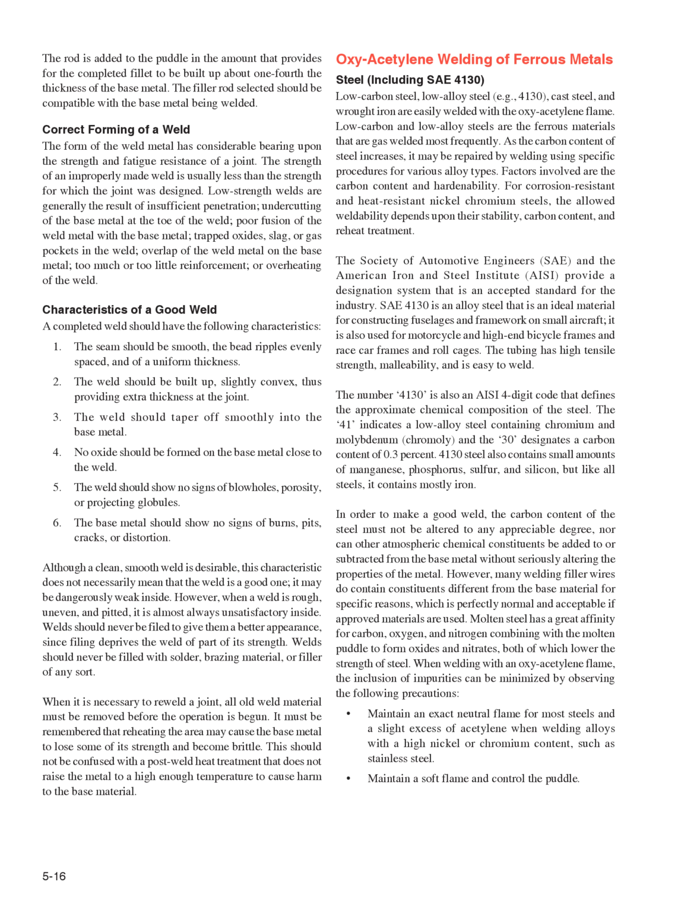In order to make a good weld, the carbon content of the steel must not be altered to any appreciable degree, nor can other atmospheric chemical constituents be added to or subtracted from the base metal without seriously altering the properties of the metal. However, many welding filler wires do contain constituents different from the base material for specific reasons, which is perfectly normal and acceptable if approved materials are used.